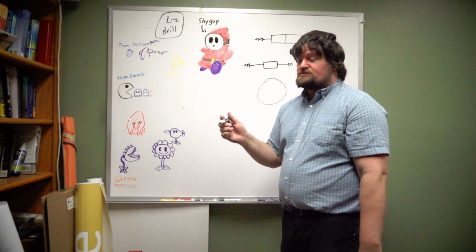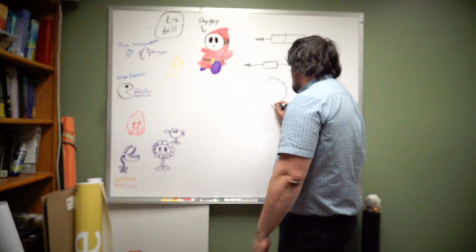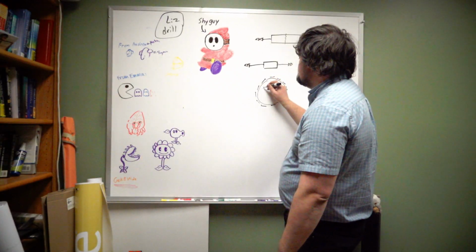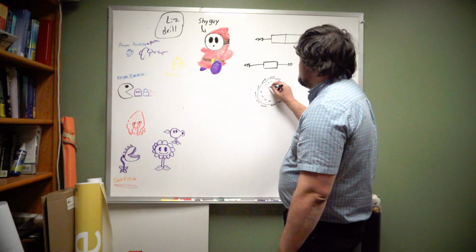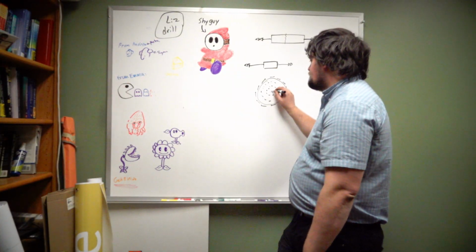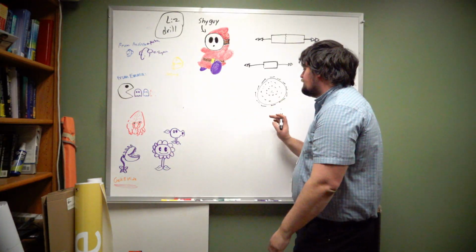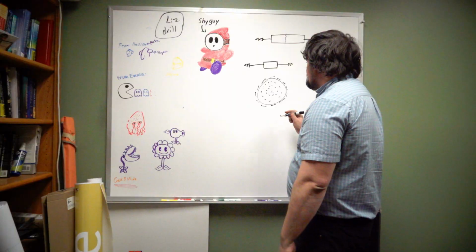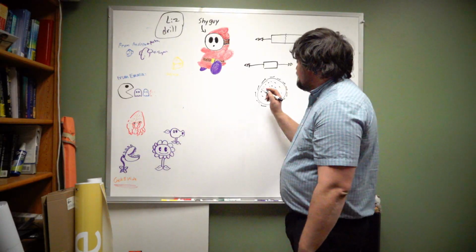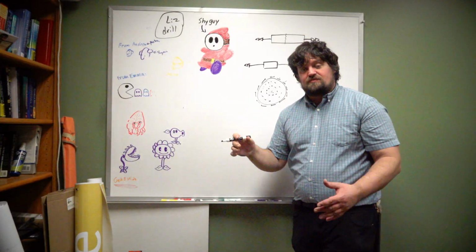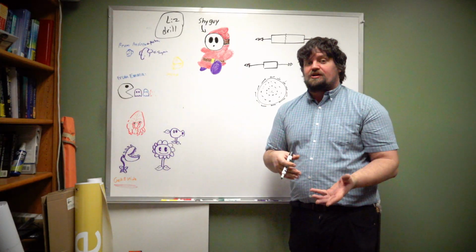What is capable of producing a moment, though? What we see is that it actually exerts a load around the outside of the object. Well, it's not just the outside, it's actually concentric bands where each one of these gets smaller and smaller, the actual loads. Loads increase the further out radius we have from the center, but all of these loads point in the same direction. And the cumulative of all of these loads acting contributes to one net torsional moment. Okay?